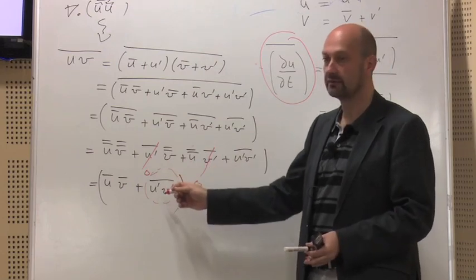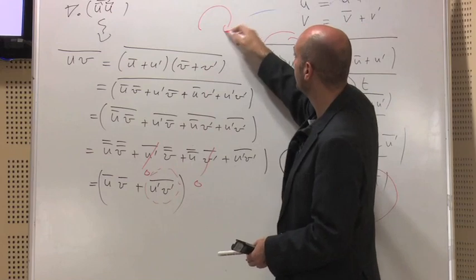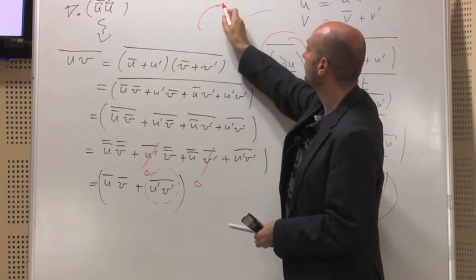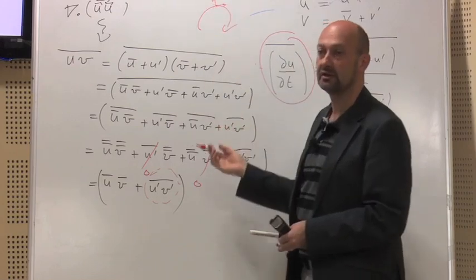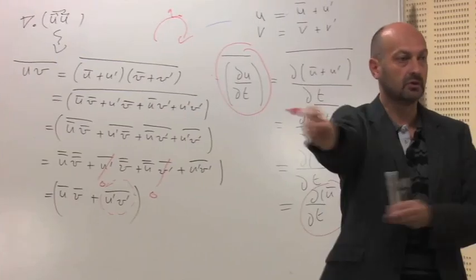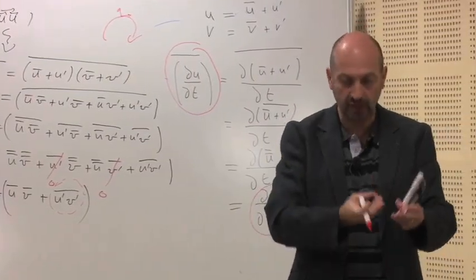But of course in a fluid there is correlation, because when you have a vortex like this, in turbulence you have many vortices, so you cannot say that this component and that component are completely decorrelated, because that would mean that the fluid is moving in different directions without any correlation, and we know that it is not the case because you have these flow structures.